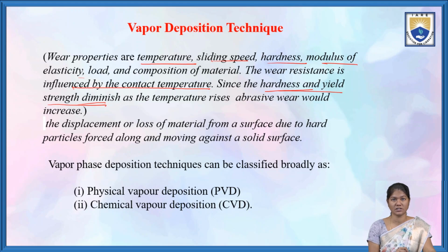What is abrasive wear? It is the displacement or loss of material from a surface due to hard particles forced along and moving against a solid surface. So this is abrasive wear. The hardness and yield strength diminish as the temperature rises, so abrasive wear would increase.